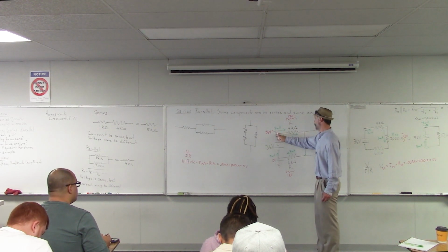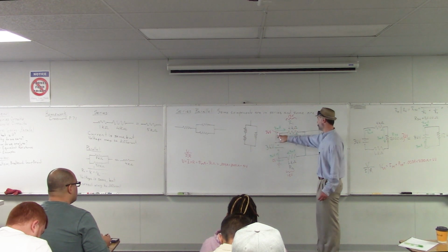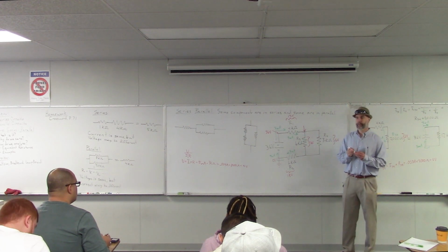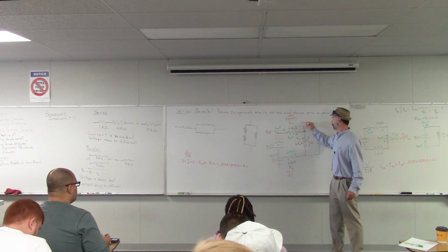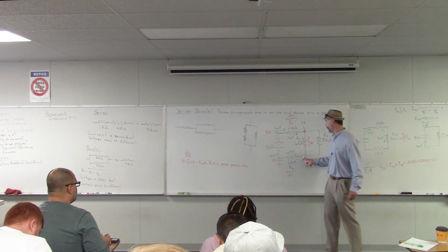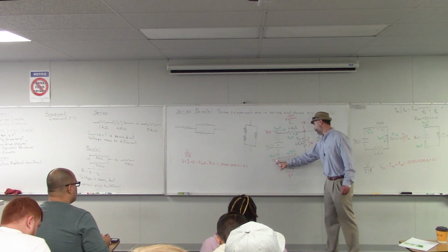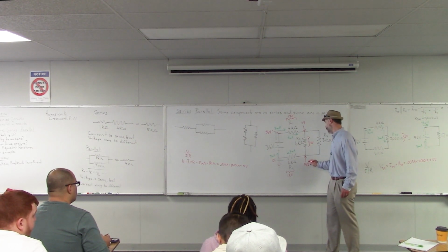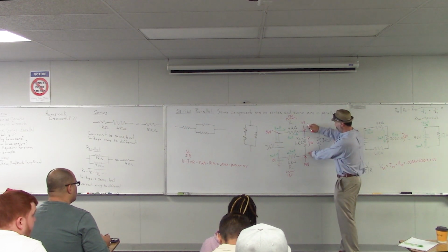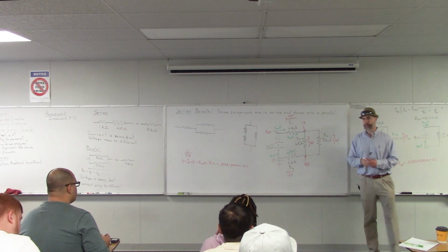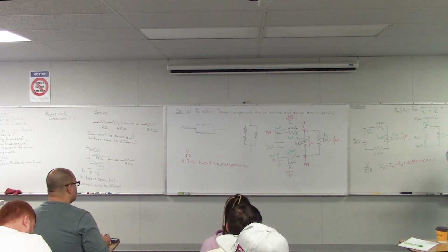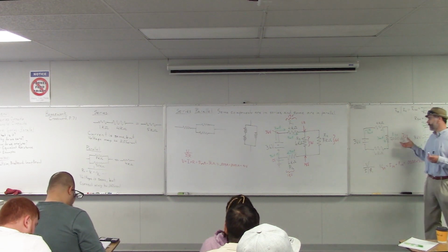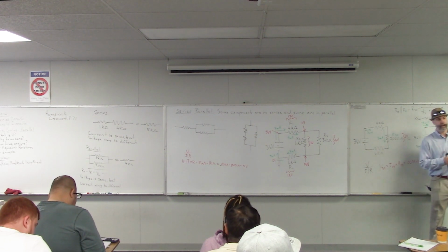And then we're going down by 12. So we're starting at 36, going down by 12. So what voltage does that leave at that point? It's 24 volts, right? And then over here, we're starting at 0 volts. We're going up by 18, so we would have 18 volts at that point. So the difference between these 2 points would be 6 volts. So that's another way to do it. Again, in electronics, there are often multiple ways of getting the right answer. So these are 2 different ways of looking at it that both give you the right answer.